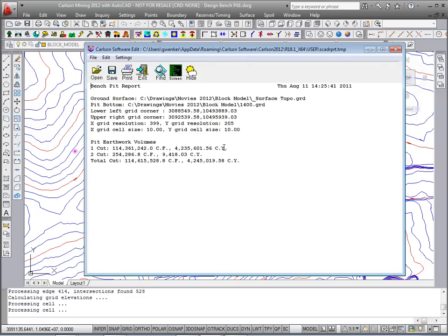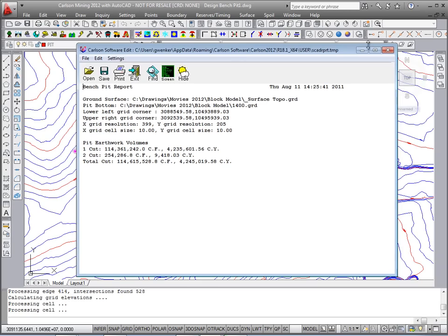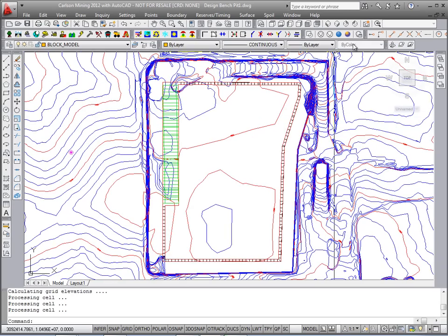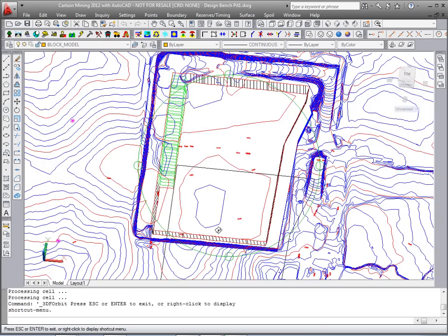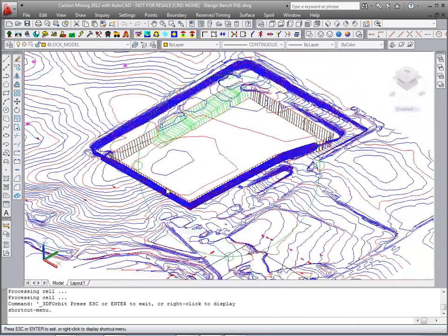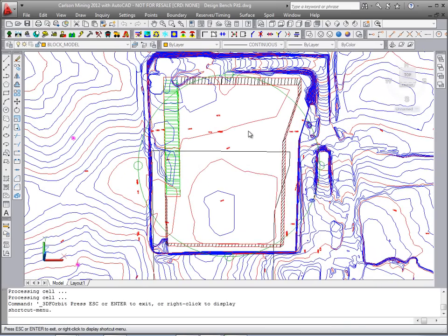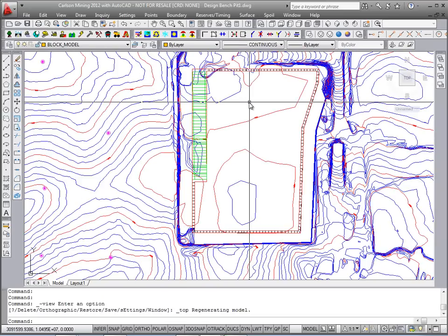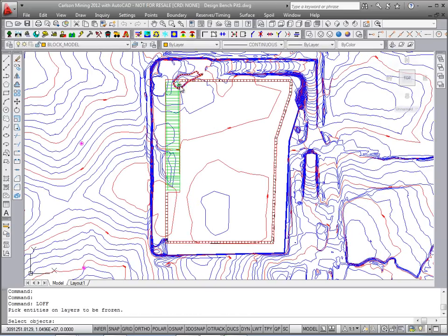And there's the complete volume, just total dirt and rock volume. And take a look at that in 3D with the AutoCAD orbit. Tip it up on the side like so. Alright, let's trim out the old contours inside. And I'll freeze the new pit lines for starters.